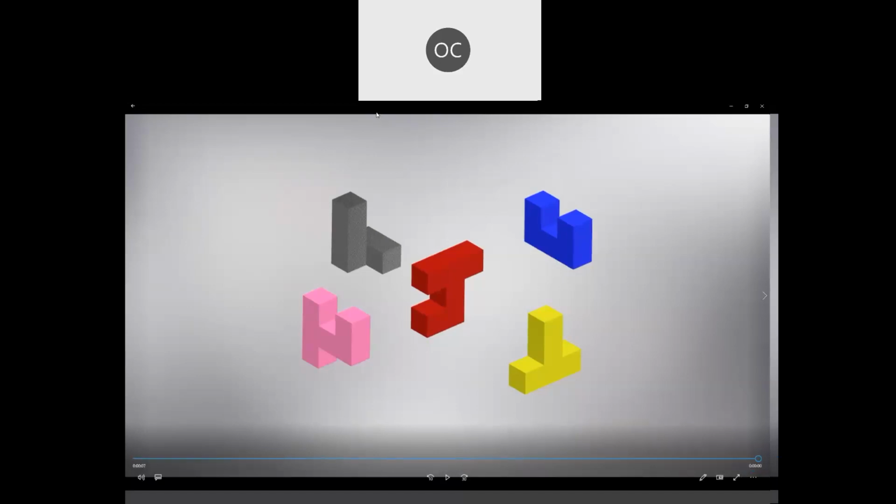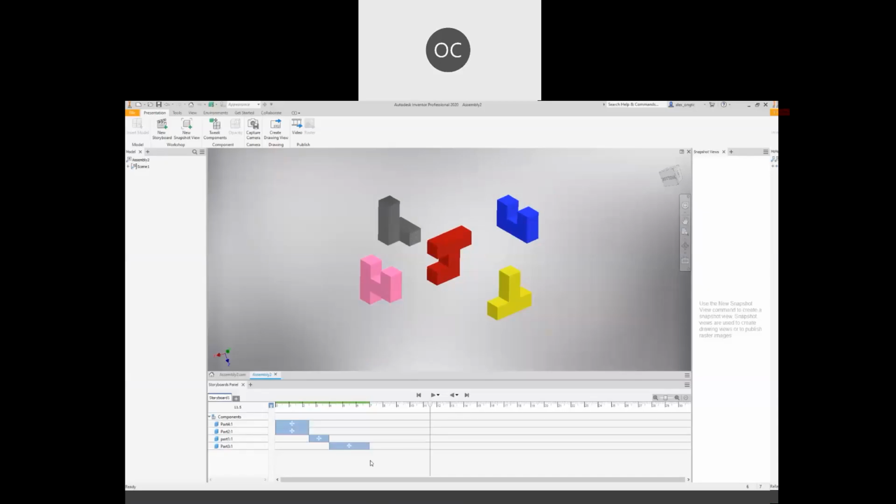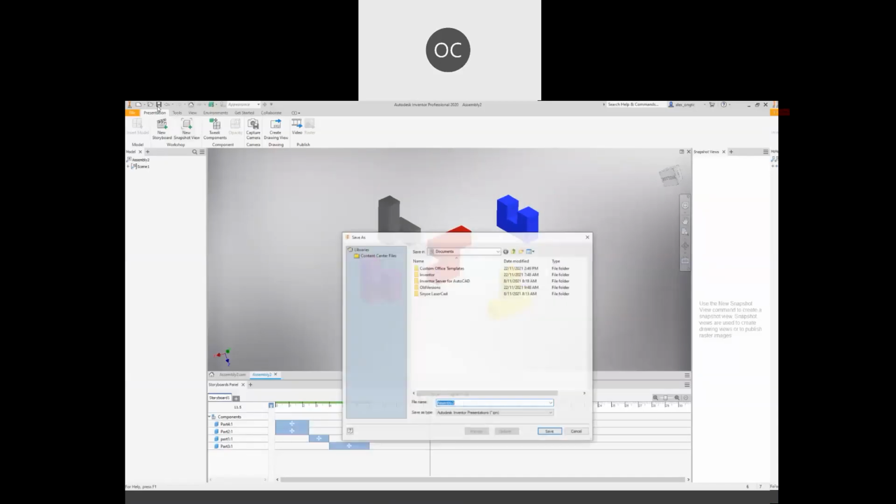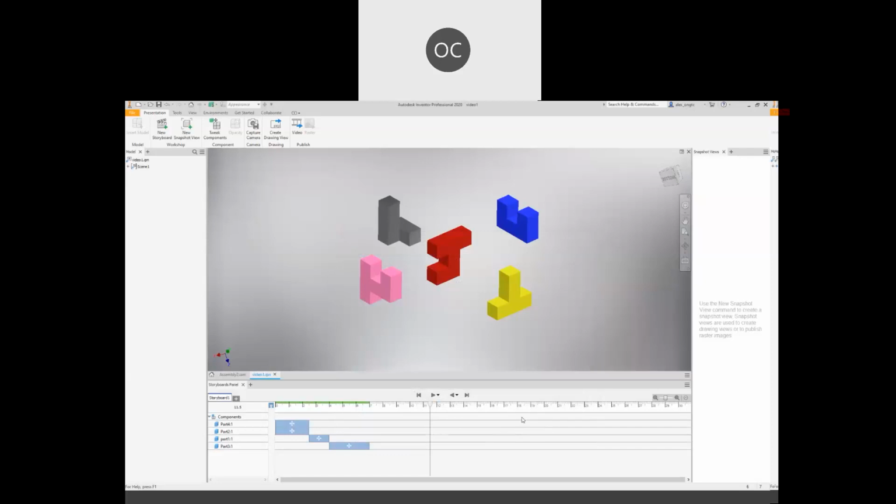So I would like you to save this one, just save this one. Later you just convert the video, you just submit the video. No need to submit this one. This one will be video 1. Just save as video 1 as IPN. When you save a presentation file, it will be in the form of IPN. Save this one as video file, video 1, in case you need to do any editing in the future, you can come back to here, and from the storyboard you can amend accordingly.